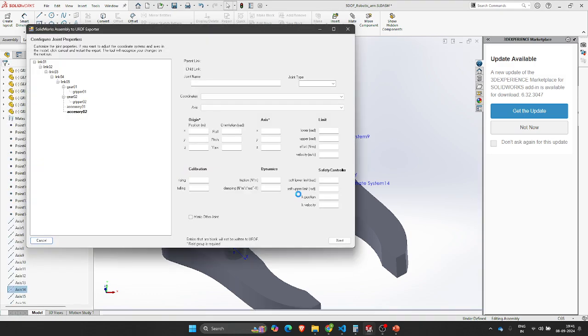See, it would take some time, and it would open this configuration tab, and you could check whether all the configurations are proper. So okay, let's say link one. There is something called the base link. The base link is always fixed, so we start from link one. Check whether the joint type is Revolute.